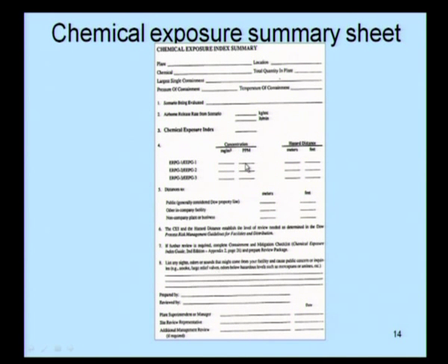If you have ppm also, you can always convert them vice versa using standard equations explained in the previous slides. Once you get the hazard distance in meters or in feet as per the requirement of the client, then enter the distance to which the public, generally considered as the Dow property line, is exposed. Also enter the non-company plant or business in meters, and also enter the other company facility in meters, because you know what is the safe hazard distance beyond which you can locate the public, the company facility, the non-company facility or any other business plant.